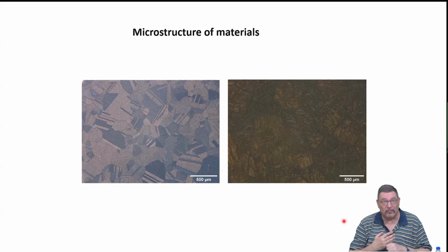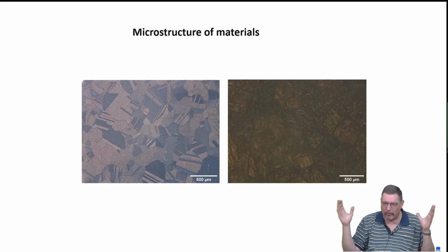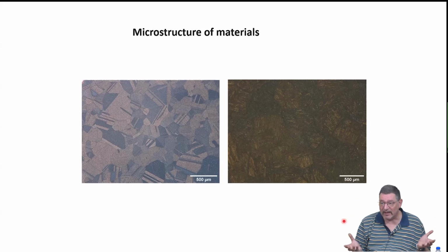Well, depending on what you did previous to the material. But if you do a normal forming process, so meaning you introduce quite a large deformation, you can easily go up to 10 to the 15. So it's really high. It's actually often approaching almost the theoretical limit. And it's very difficult to get rid of them. So if you anneal them at the typical temperatures, 0.75, 0.8 of the melting temperature for a few hours, you will see that the decrease in dislocation density is not very high. So they are really retained.